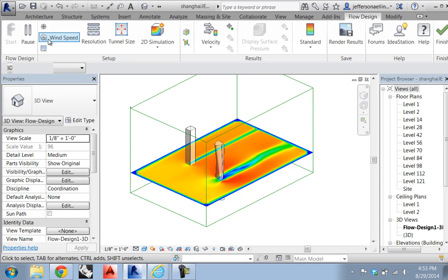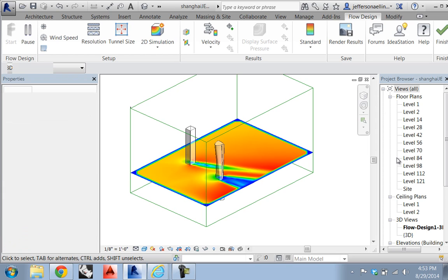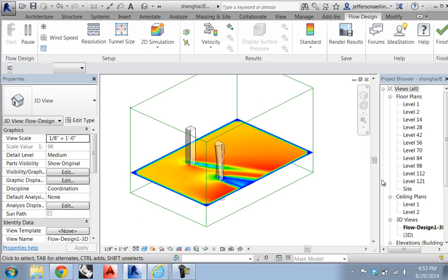Also, just very quickly, here you have, I don't know why the text isn't showing up, but it's not. Here's where you change your wind direction within Revit, this is radically different than the way it works within Flow Design. So obviously, as you look at your wind roses, you can sort of populate your airflow based on the way the wind roses look in your research.